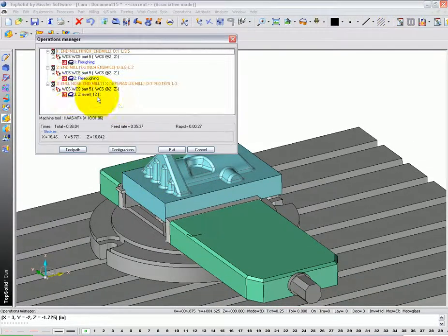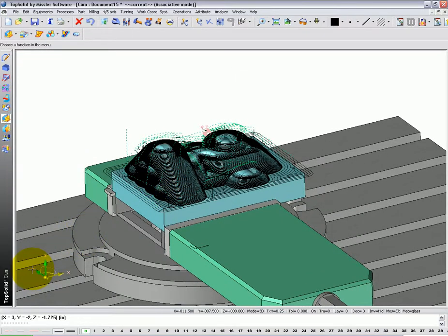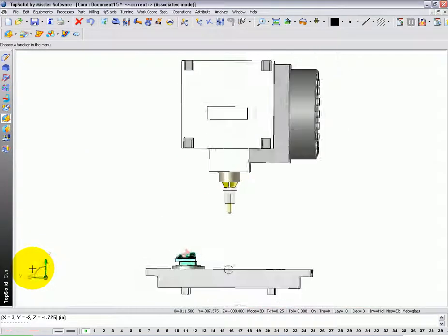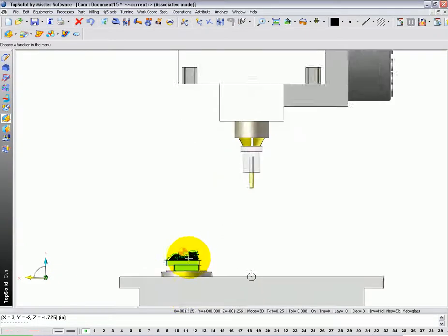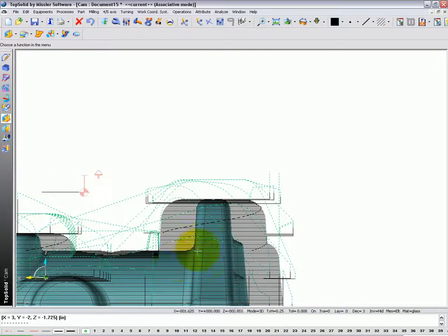Let's go to the Operations Manager and visually turn on that toolpath. And now let's click on the Y button by our compass down here. Doing that will make us look straight down the Y-axis. And now use your scroll wheel of your mouse to zoom right up on the model. First of all, you see how the rapids are all in three-dimensional space? This is that rapid type that you specified that will actually act as a rubber band rapid.